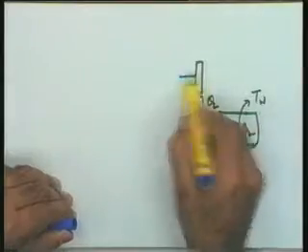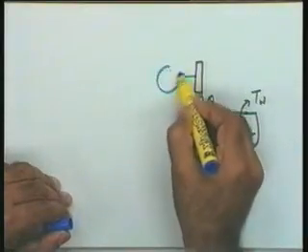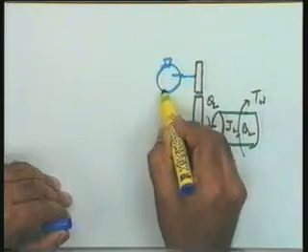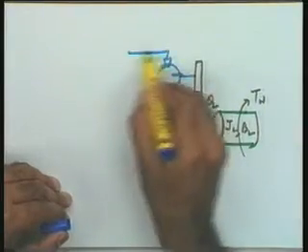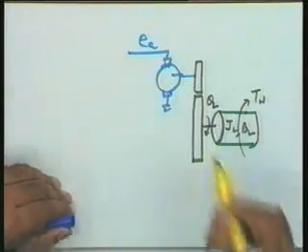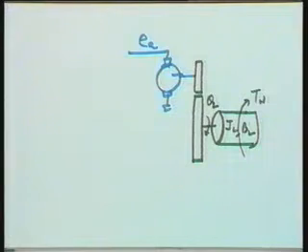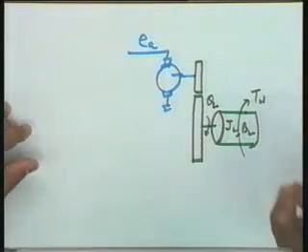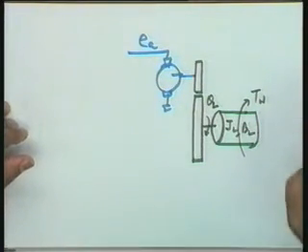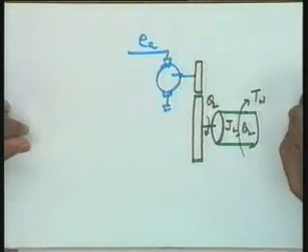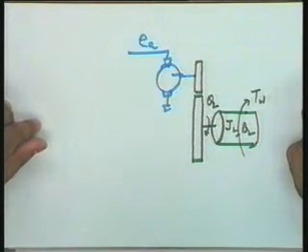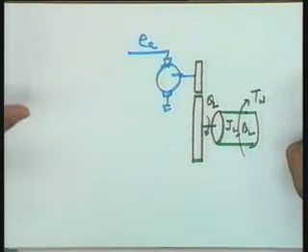So it means this primary gear is connected to a DC motor. This is the armature voltage E_A, which is the controlling signal. This is one constraint. Another constraint is that instead of a potentiometric error detector, I want to use a synchro error detector. The reason?